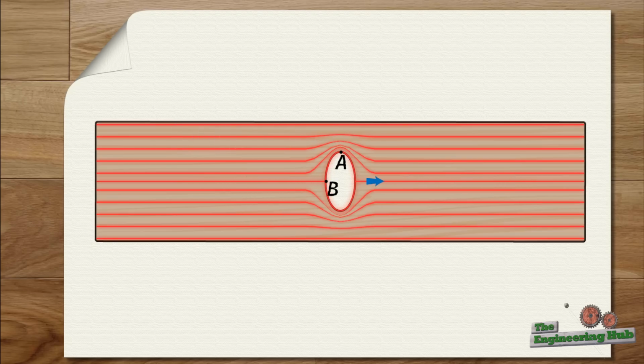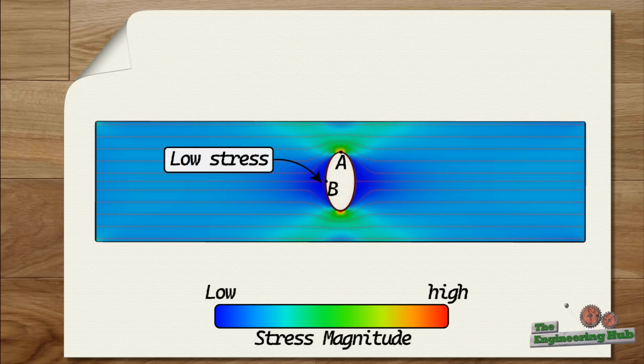And sure enough, looking at the stresses from a finite element solver, we see a horizontal normal stress of nearly zero around point B, since the fluid has to slow down to make the turn around the hole, resulting in a low horizontal velocity. At point A, the fluid speeds through the tip of the ellipse, resulting in a very high horizontal velocity and hence high horizontal stress.